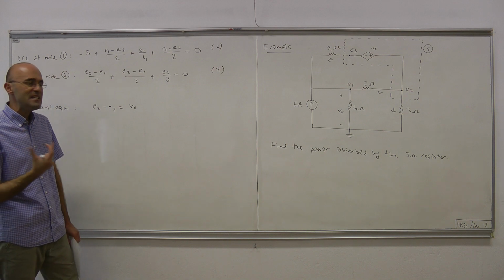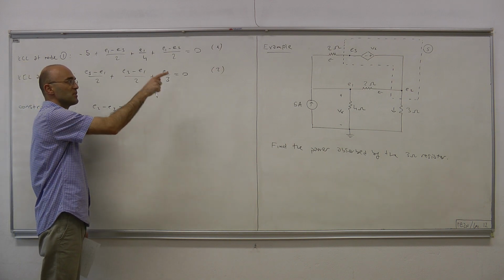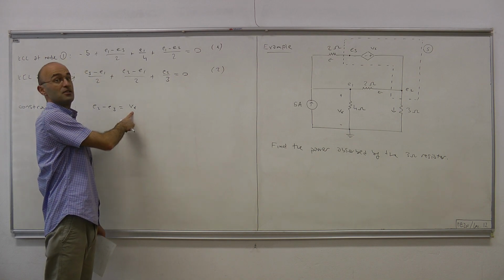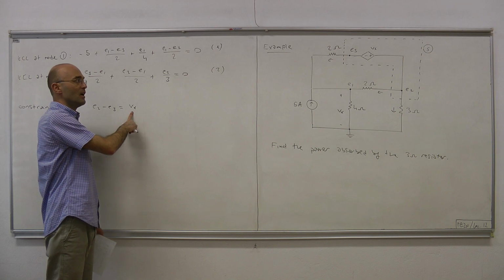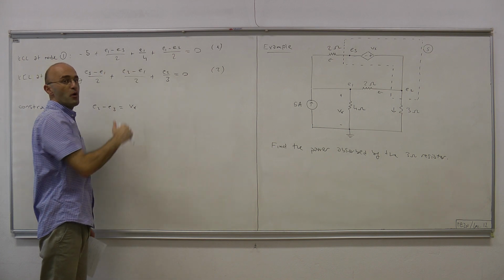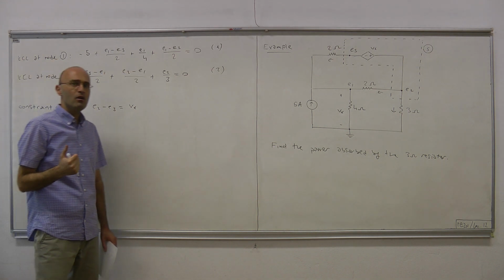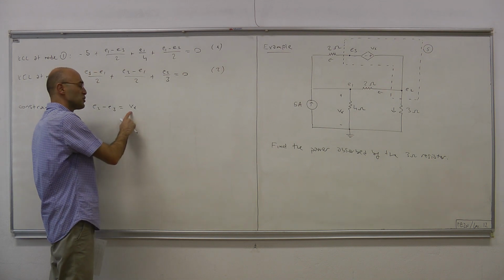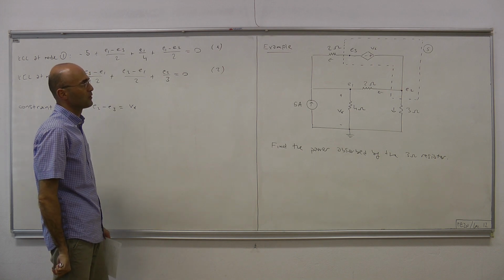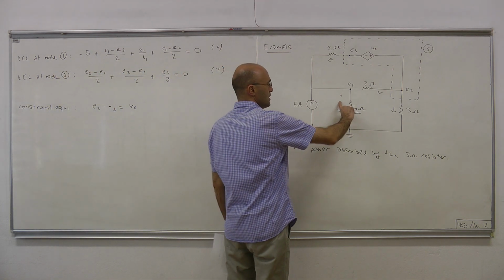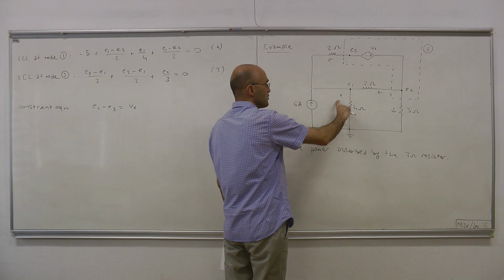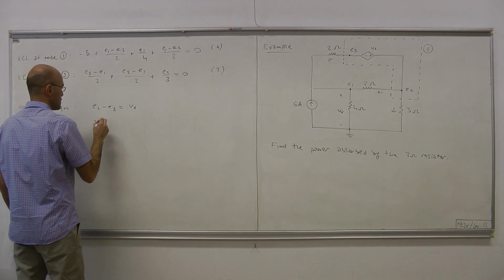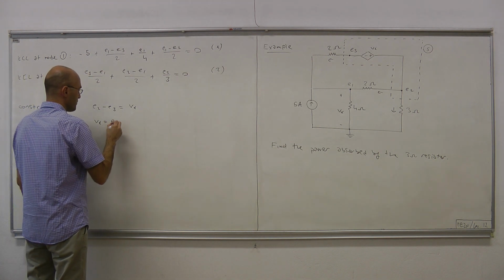Okay. Note that we cannot leave this equation as it is, because that's a dependent source, meaning that we don't know what Vx is at this stage, at least. Okay, this is also an unknown. But in our equations, the only unknowns that we allow are our formulation variables, namely E1, E2, and E3. Therefore, somehow we have to express Vx in terms of our node voltages. So Vx is this voltage, and this voltage is simply E1. Therefore, we can express Vx in terms of node voltages, E1.